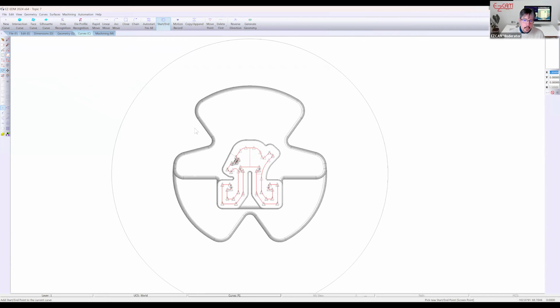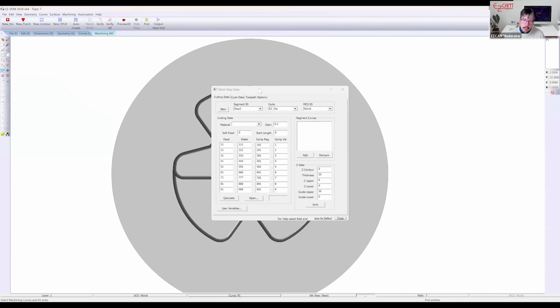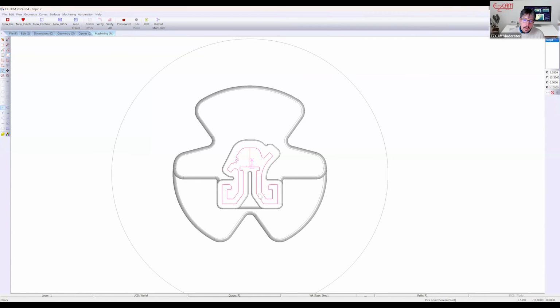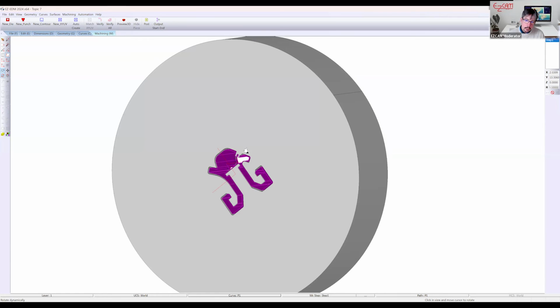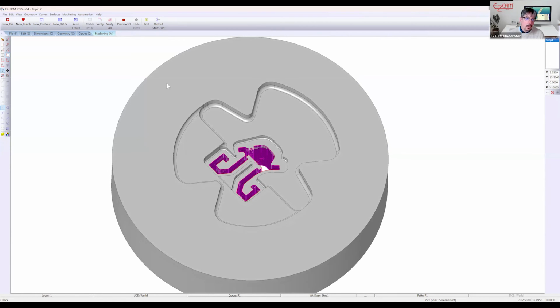Let's do a top view. That is going to be a die. Straight wall. Pick our curve. Verify our toolpath. And we have another case where we want to bring our wire guide up to the top. So I'll use snap to all. That gets copied to the clipboard.